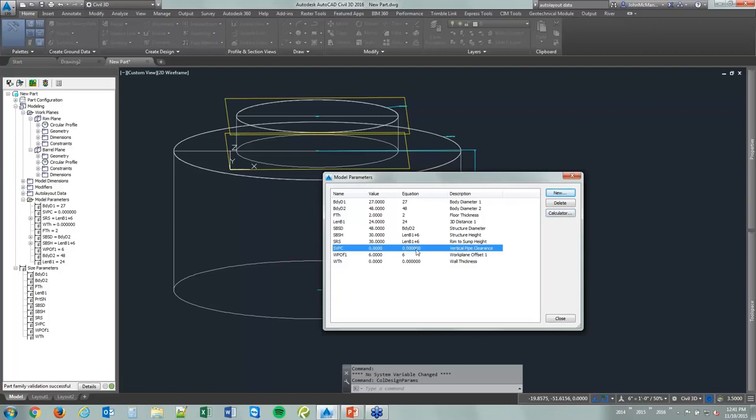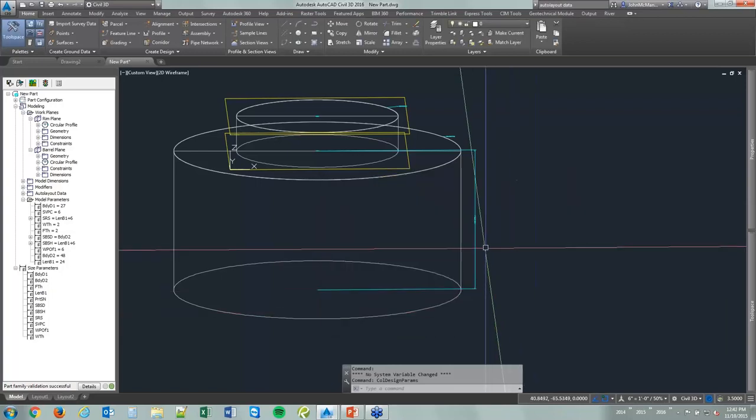Vertical pipe clearance, again, maybe you want to use it, you have a defined value you know that you want here. Maybe not. I'm going to set mine to be 6 inches and my wall thickness to 2 inches. I don't plan on using it typically, but don't leave it at 0. That's my advice to you.